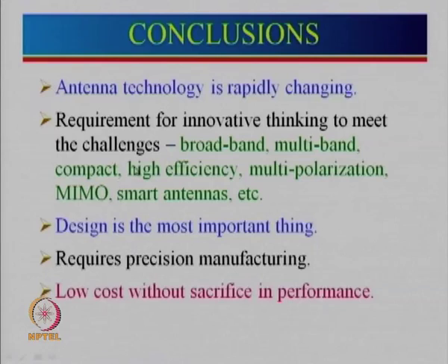Also, there is a demand for smart antennas. Now, again, smart antennas can have multiple things which are smarter than a normal passive antenna. So, many a times all the antennas are in general passive antenna, but we can make them smart by integrating maybe oscillator within the antenna or amplifier within the antenna, or build signal processing technique along with that, so that we can have adaptive antenna array and so on and so forth.